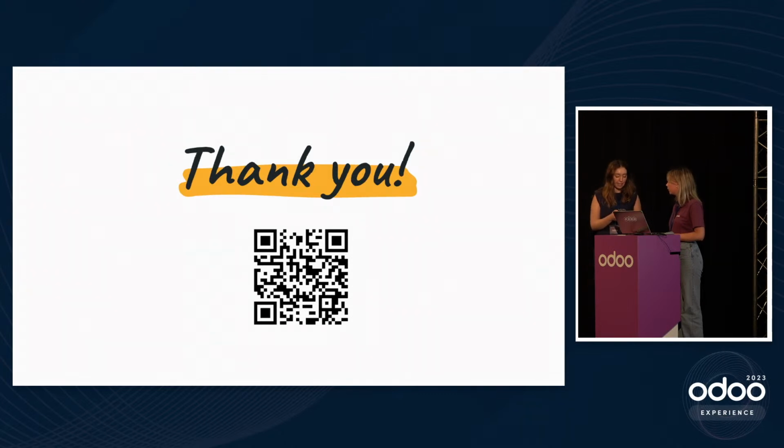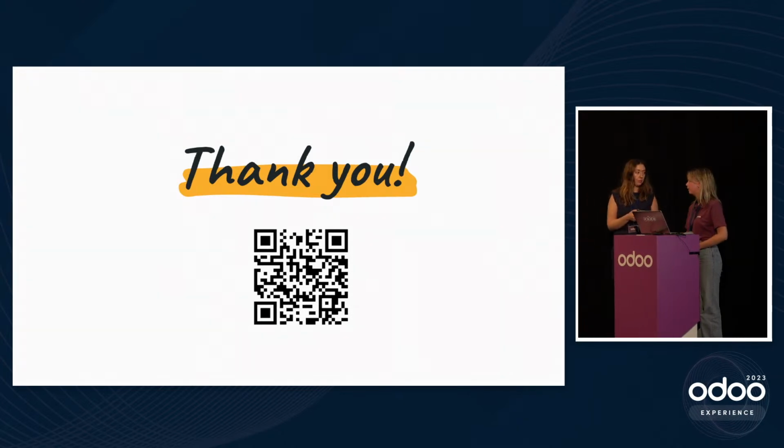So when do you advise to use the generate bill of material feature versus the PLM? Good question. So the generate BOM, you will use it when you need to create a BOM really from scratch. But then if you want to do some modification, you could create an ECO directly from your manufacturing order so that it could be linked with the PLM. So actually that could also be a possibility in the flow.